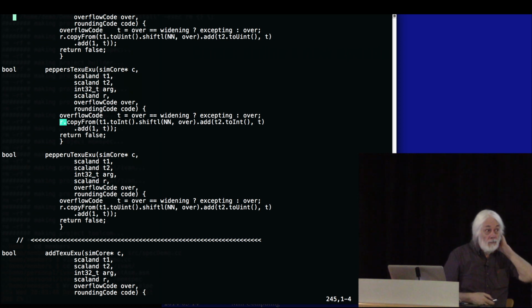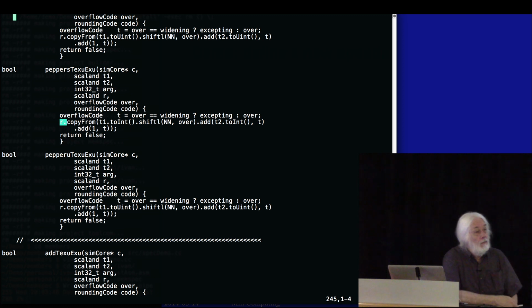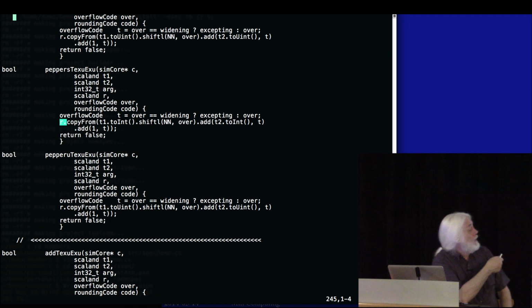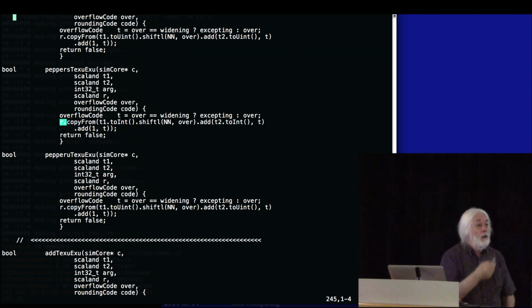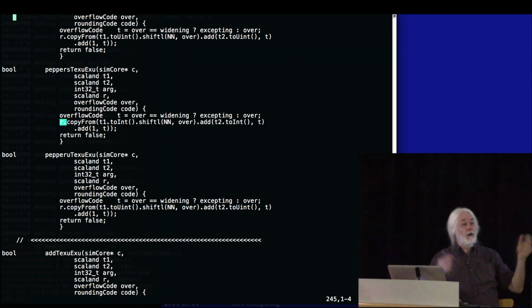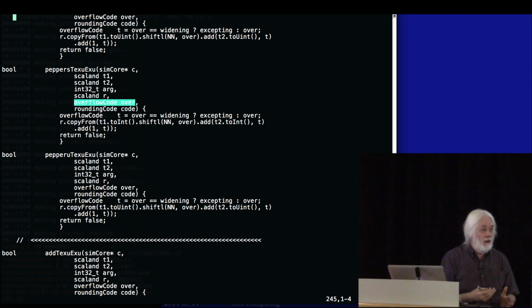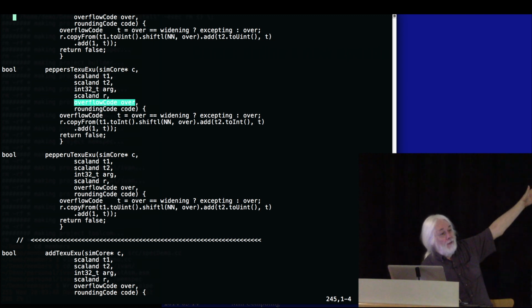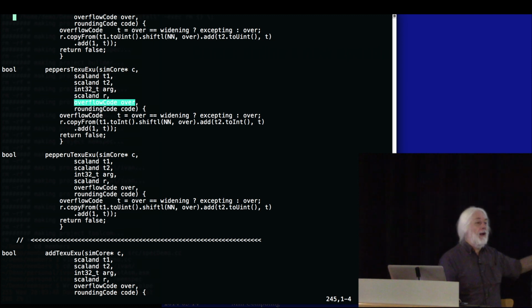Well, then how does a programmer specify saturating or some other overflow process? When you write it in the assembly language, that means a separate mnemonic. Where does it show up here? It doesn't. Because we haven't defined it here? No, it has been defined. The tools know about overflow behavior, effectively removing that out of the mnemonic, so you only have to have the cases which do not handle that, and treat overflow as an argument rather than as a different function call.